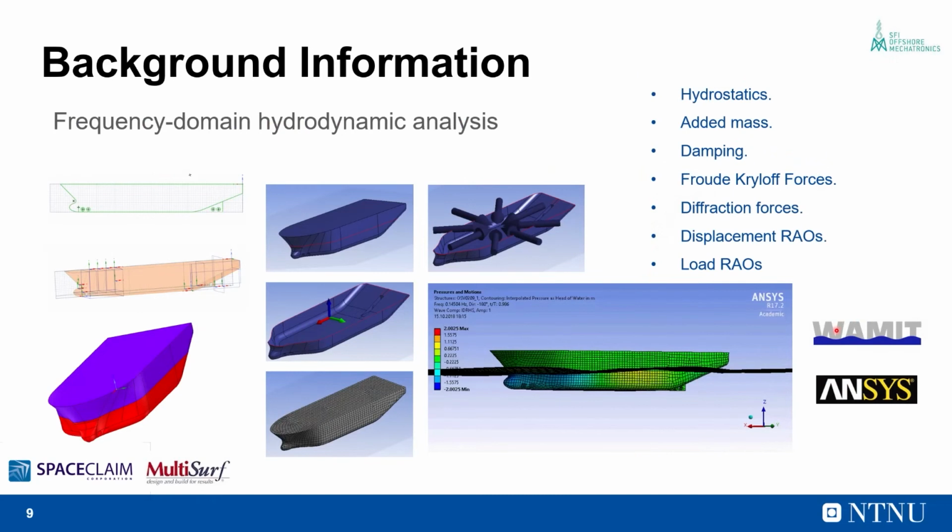In practice, the frequency domain hydrodynamic analysis is carried out using software like WAMIT and ANSYS AQWA, which use the panel method. So in the panel method, the body surface is first modeled. It is split at the waterline. The center of gravity and the moment of inertia are specified. The surface is discretized into panels. And the wave directions and frequencies are specified, and the analysis is carried out.